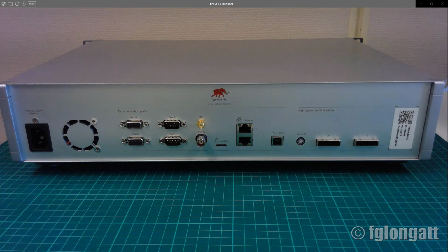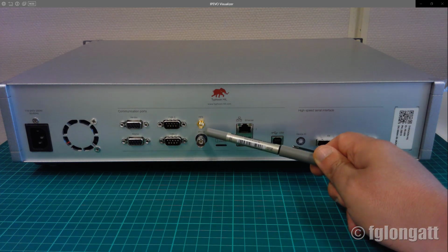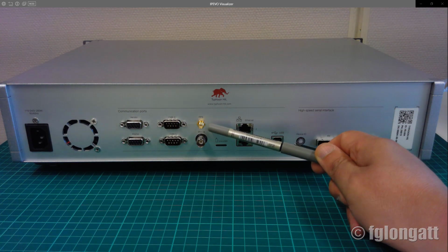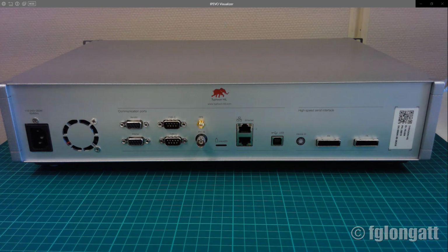As you can see, there is one with the initials IRIG-B. Those are the initials for the Inter-Range Instrumentation Group time code. What is this? It's basically a standard format that is used for transferring timing information. Later we will have a video, because this communication port will be used for some testing, especially for phasor measurement units.